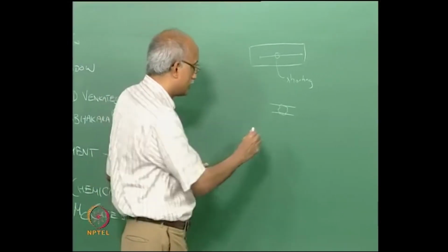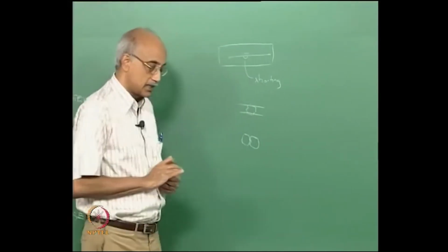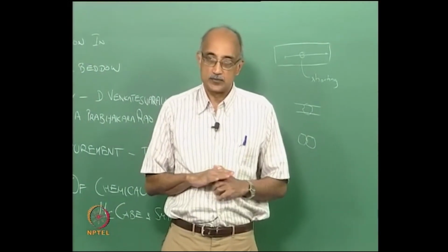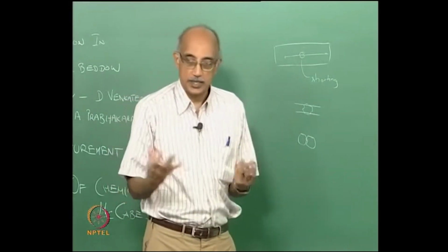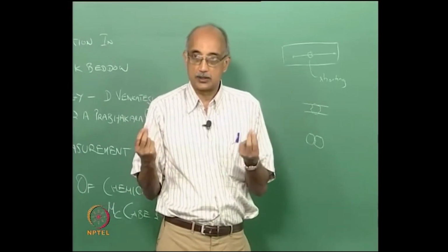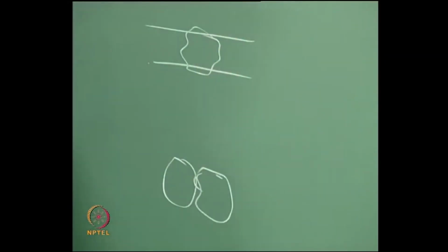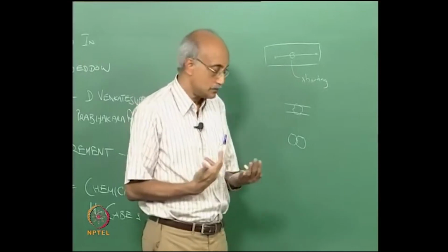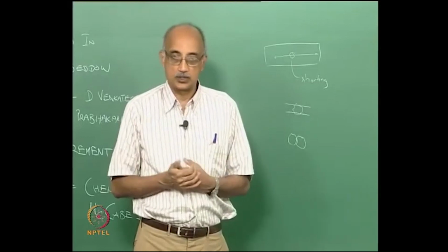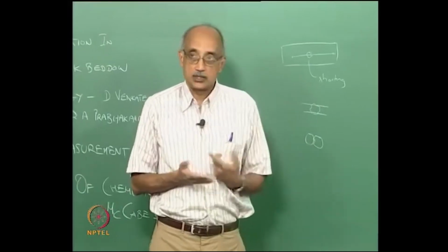Now, when we talk about particle to particle cohesion, this again for the most part is something that you want to avoid in manufacturing processes. The whole reason for preparing a particular slurry or a suspension is to keep the particles separate and isolated as particles. So, it kind of defeats the purpose if 2 adjacent particles simply come together and stick to each other. So, in this case, the particle to particle adhesion in a medium, which is also known as cohesion, is something to be avoided. Now, there are many reasons for this.